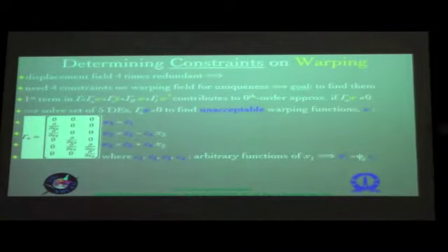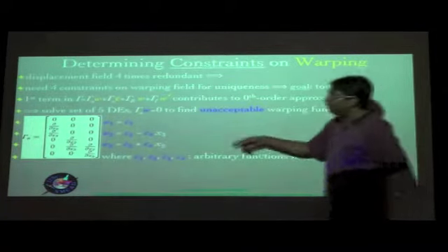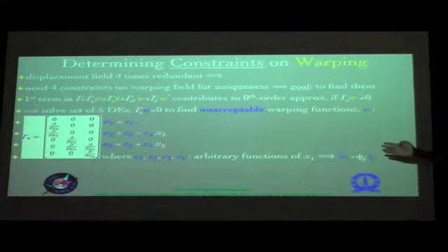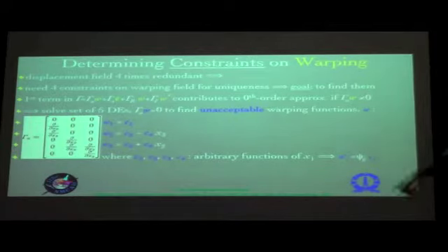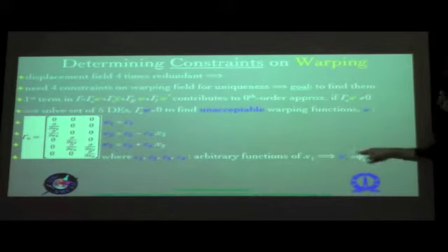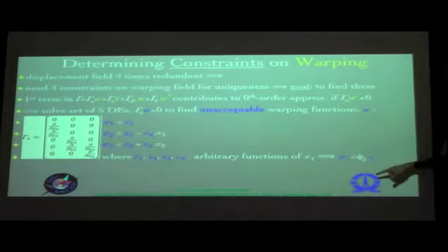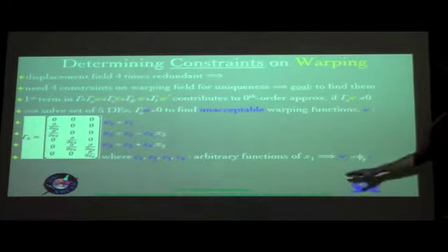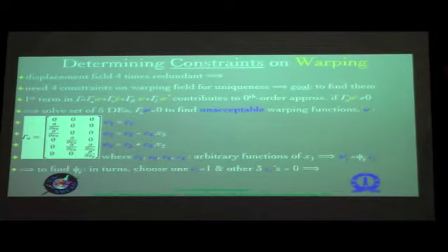And there is a way to write this set in terms of the constants that you have determined. There are 4 constants, C1 to C4, and you have 3 unacceptable warping measure numbers, W1 to W3, and these two can be related in terms of a so-called kernel matrix, which is basically multiplying this column matrix of 4 by 1 to give another column matrix of 3 by 1. So that's basically what you have here.